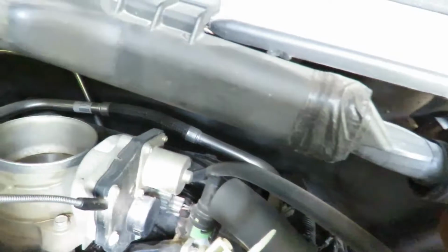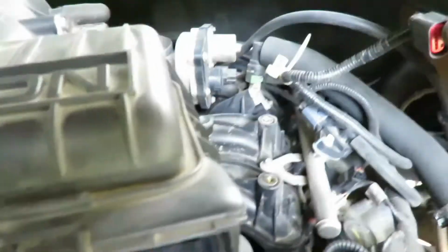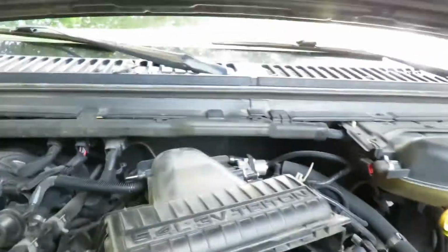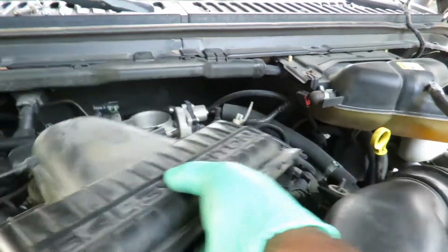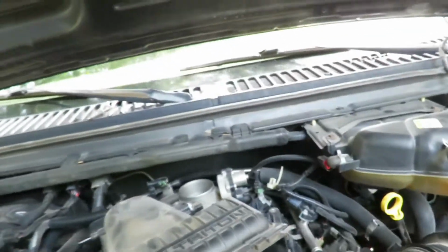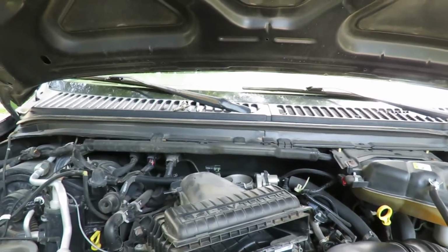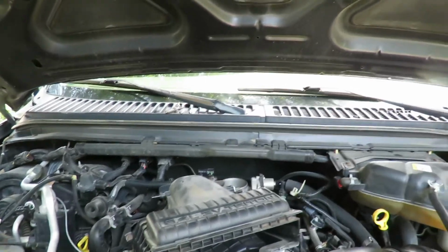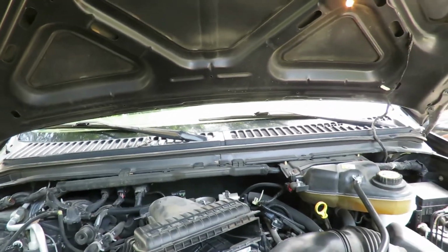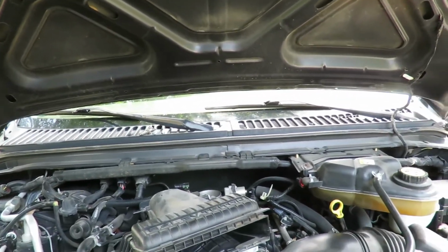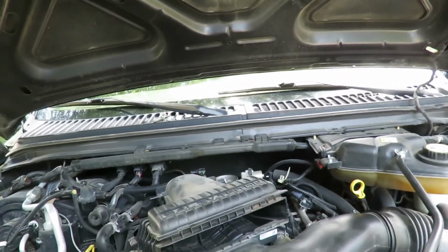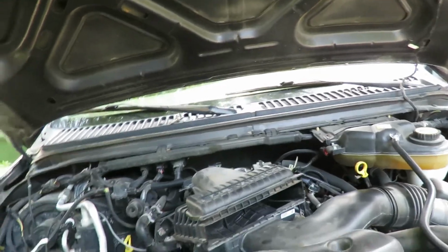Man. The problem is, we can't get a gasket for that today. Dang it. But I still want to do a graph on that fuel pump. So this is definitely one issue, and this is definitely what will cause that P0506. This has got to be taken care of before anything. Alright, I'll be right back.